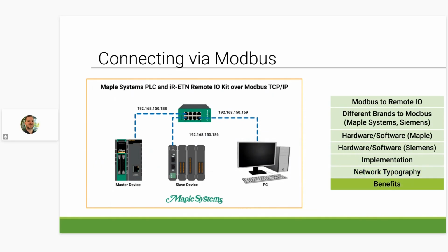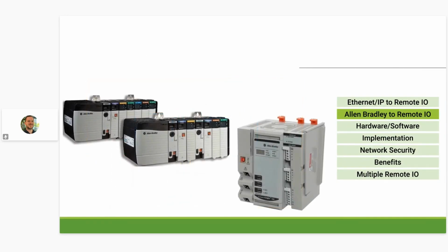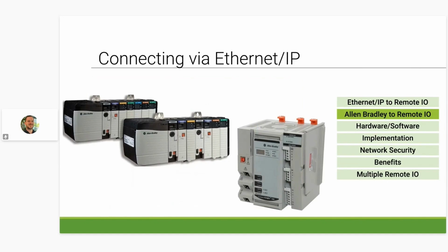Some of the benefits of communicating via Modbus, as we have briefly touched on, are its simplicity, compatibility, and flexibility. Given how long Modbus has been around in this industry, there is a bounty of resources and knowledge on the basics of Modbus communication, and it has become more or less a standard to adopt for many manufacturers, making implementing Modbus devices seamless. Another common communication protocol that you will see a lot within industrial automation is Ethernet IP.